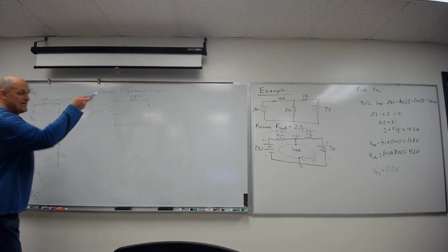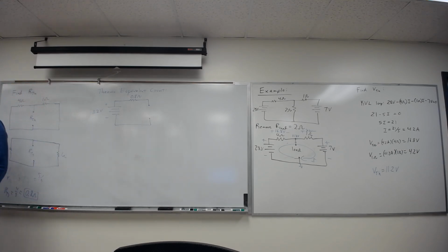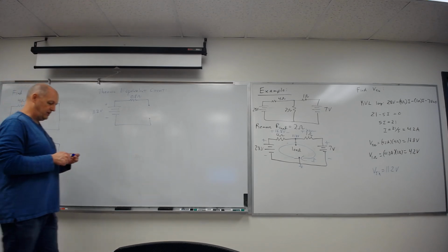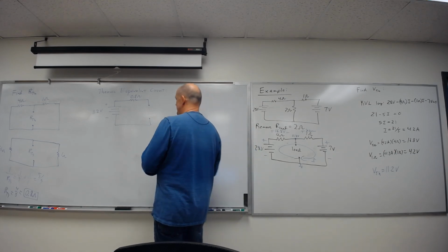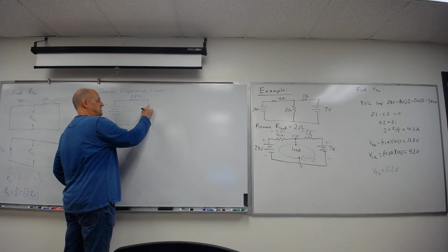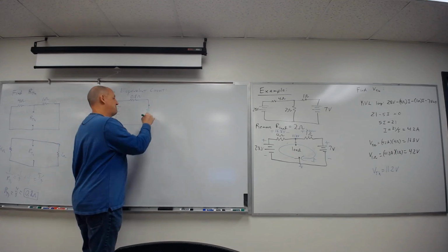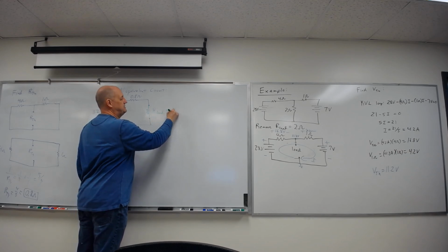So I'm going to reduce that entire circuit down to a single equivalent source and a single equivalent resistance. Those are the Thevenin values. If I would like to now, I can take that original circuit and put my load resistor in, because it's not really a circuit until I add a load resistor, right? And the load is the initial 2 ohms.